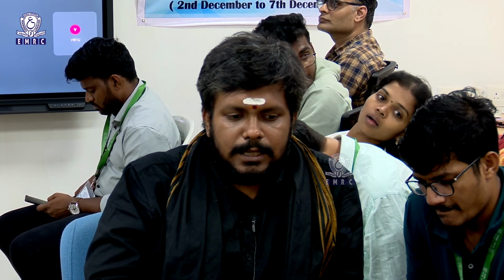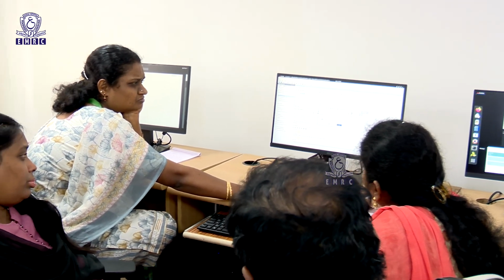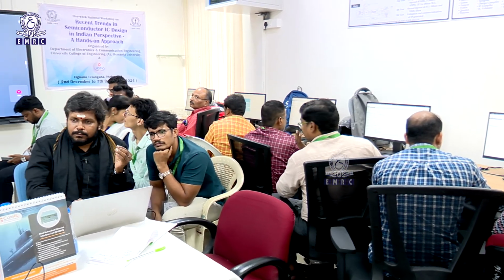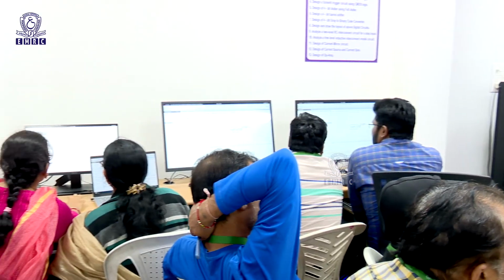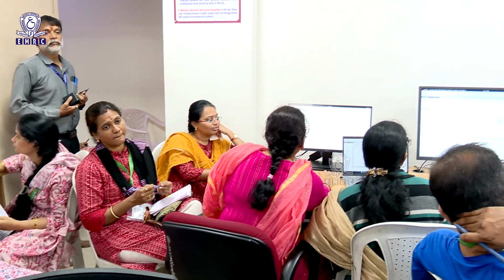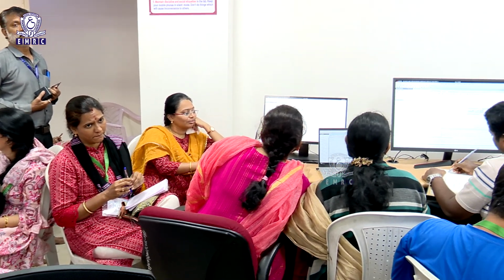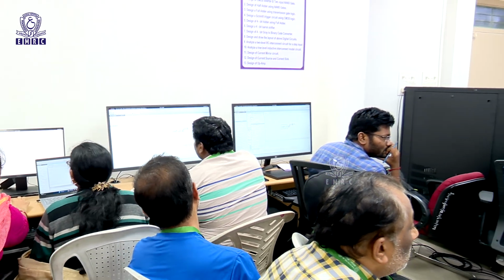So what we'll do is we right click on the block design. Okay, we are able to see multiple options here. Two things we'll do are create the wrapper and, second, generate output products. What a wrapper is we have already seen. Generate output products is needed because this is a pre-built design. The logic inside a design is not going to hinder us. The only thing that we care about right now is what the inputs and outputs are, what ports are available to me.